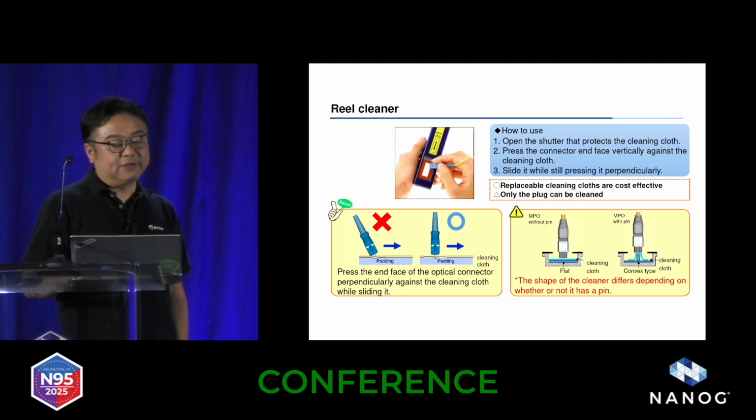If you apply too little pressure, the connector will not be cleaned. So be sure to apply firm pressure while cleaning it. And please note that for MPO connectors, sometimes dedicated types of cleaners are needed for the ones with pins or without pins.